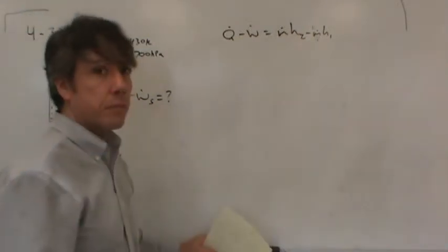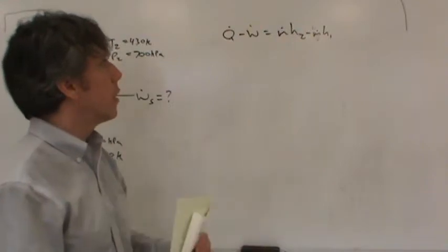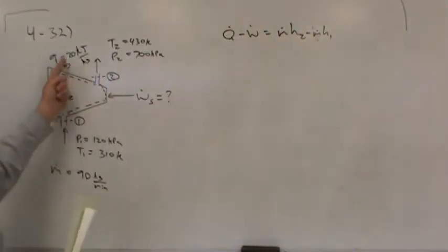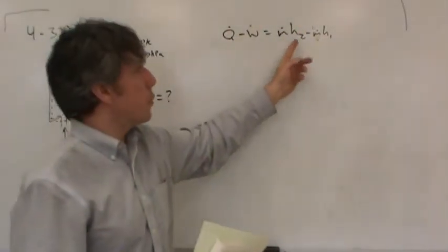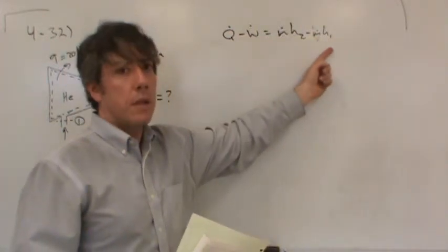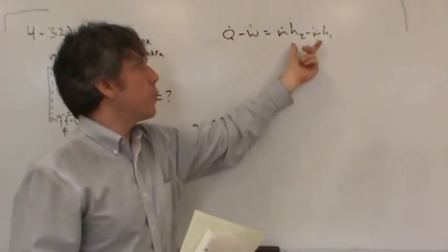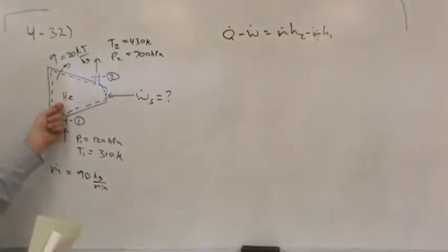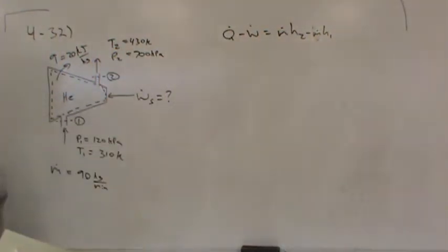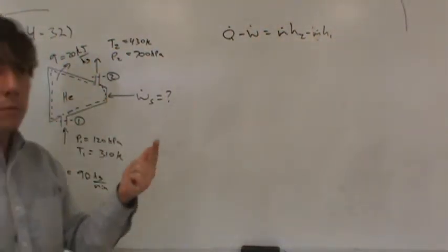Enthalpy has heat in it, but this is an additional heat loss. Q is this heat loss. Don't think of enthalpy as a heat loss. Enthalpy is not a heat loss. Enthalpy has to do with the energy of the flowing stream in its thermal and flow forms.